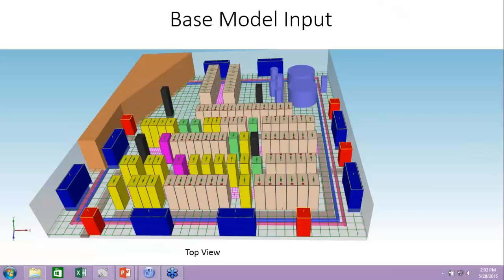Or put in another way, a lot of the data centers prior to 2000 timeframe were designed for 20-25 watts a square foot. They're primarily telecom switches and head ends. And as the internet came up into 2002 and beyond, we're looking at 150 watts a square foot and 2N design distributions and things like that. So this is very common.